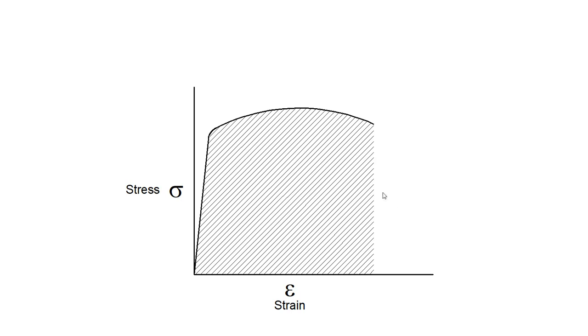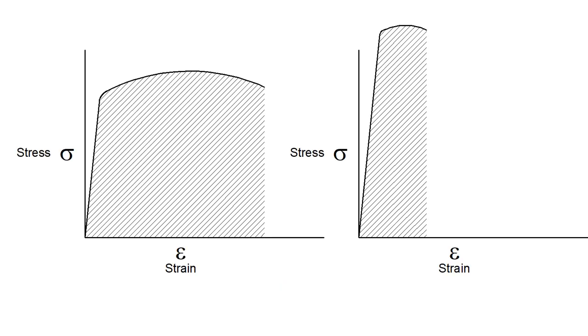So what happens when we heat treat a material? Well, it starts to look like this. So when I say heat treat, I mean a hardening heat treating process. So if we harden a piece of O1 tool steel, for example, we'll go from this nice ductile tool steel to something that, notice, the yield point has been raised up on this thing, so it's going to be more difficult to get it to flow, to get it to yield at all, and then there'll be less flowing over here. So this will absorb less energy.